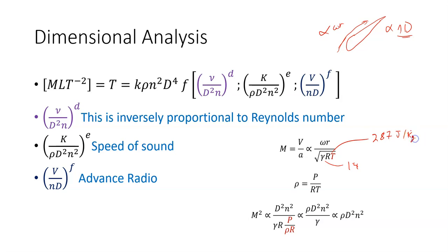No, per kilogram. Joules per kilogram. And this is the temperature. Okay, now if I take the universal gas law, which is, you know, the density is equal to P over RT, and if I transpose that, I'll get T is equal to the pressure over the density times R. So I'm going to substitute that back in here.